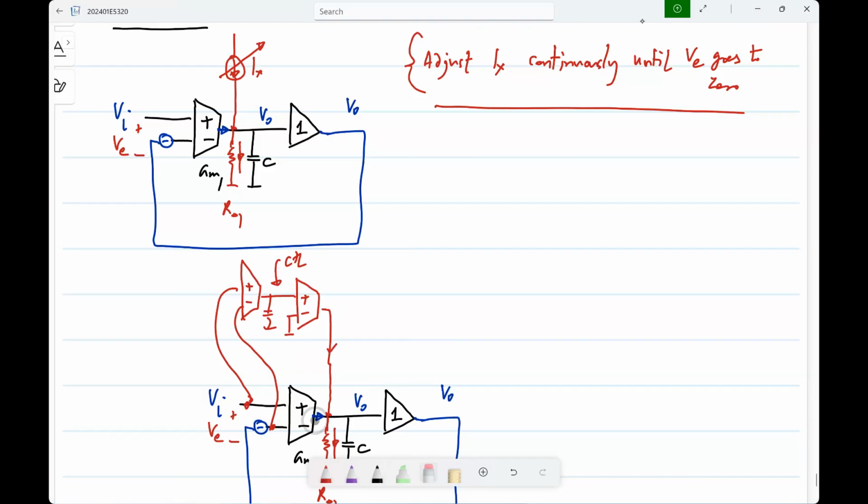No. The current coming out of this GM should be 0. Right. It will be, because if this goes on changing, when will this stop? When V is 0. And when V is 0, obviously this current will be equal to that current. V is 0 means this current is 0. And again, under DC conditions, that and that will be equal. So we've got our ideal virtual short, have we? Or is there some catch here?